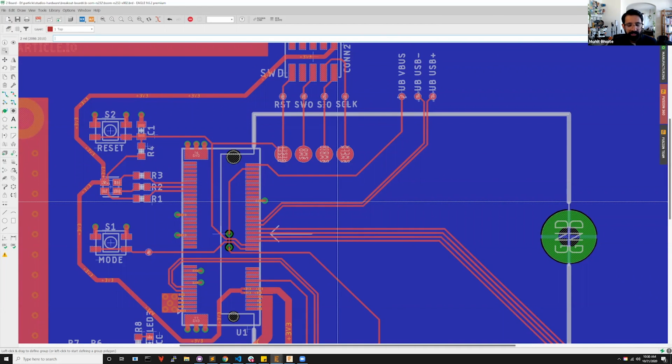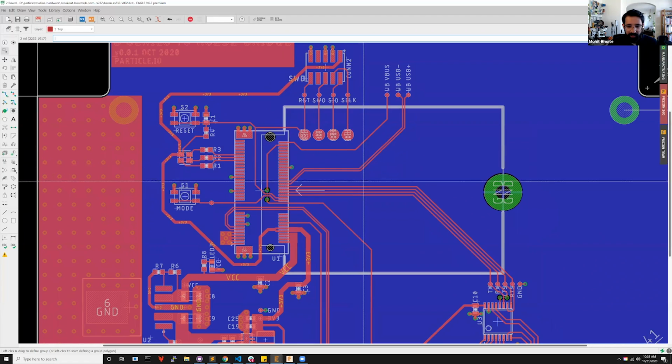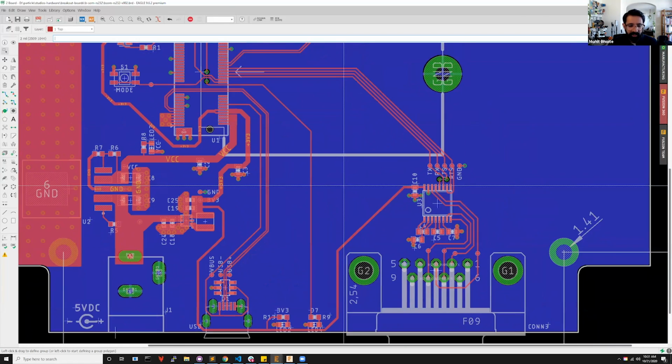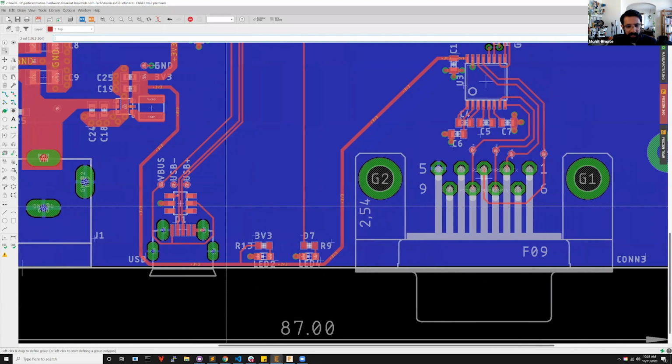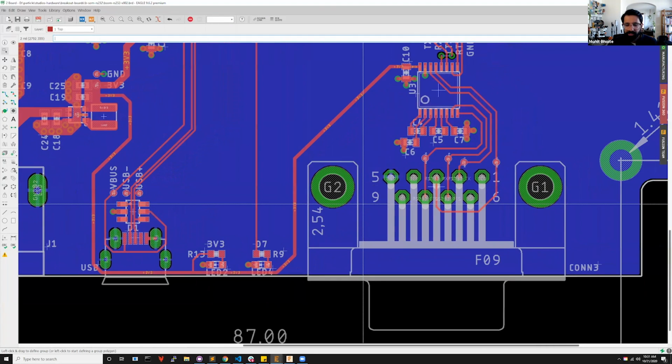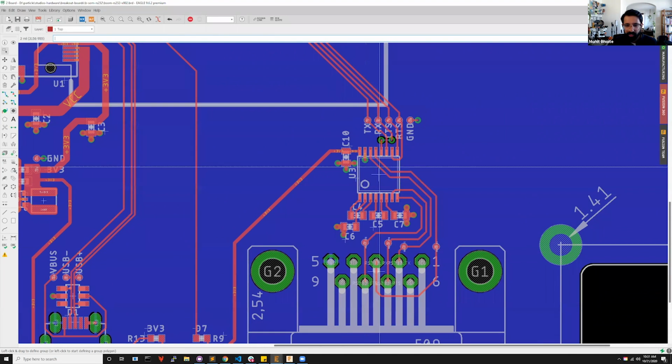And so if you wanted to update the firmware on the modem, the Quectel modem or the u-blox, sometimes these vendors will give out updated binaries that need to be loaded. And the best and secure way to do that is through a physical interface. We recommend these test points, but I don't think you would end up using them. Again, footprints are free, board respins are not, and so it will save you a headache. We have a USB connector with ESD protection, a couple of status LEDs, and a DB9 connector with the voltage translator.